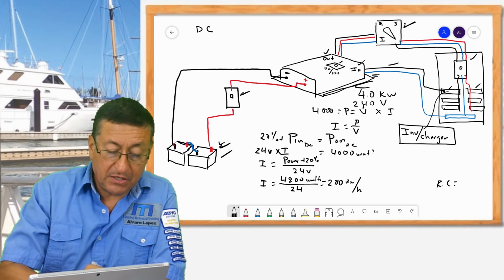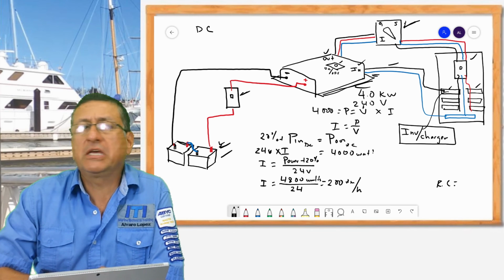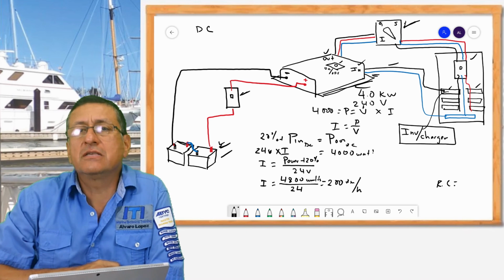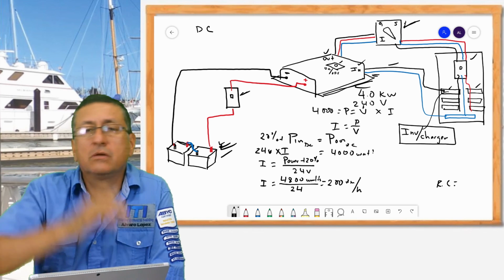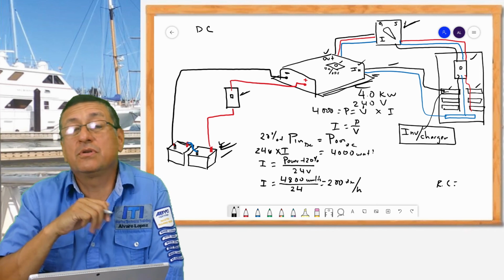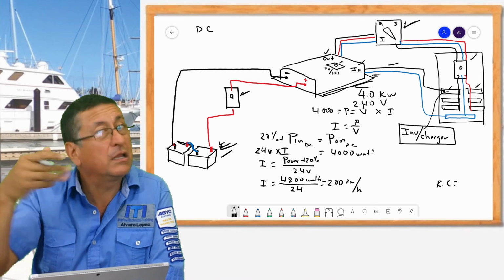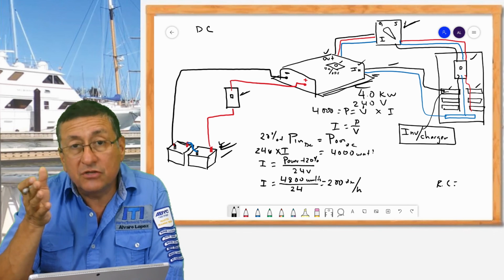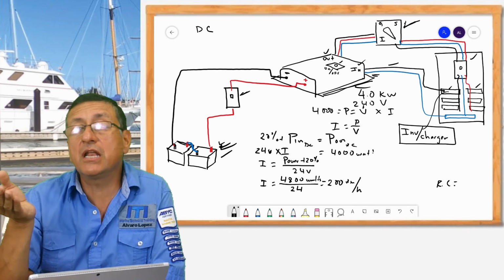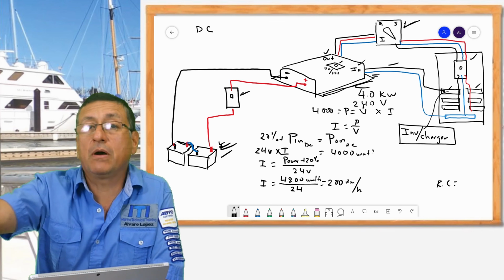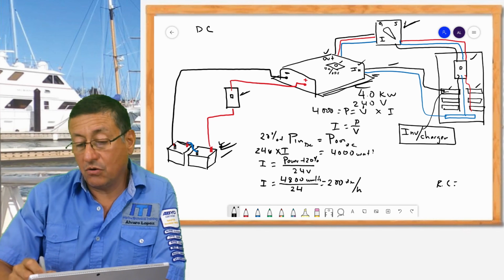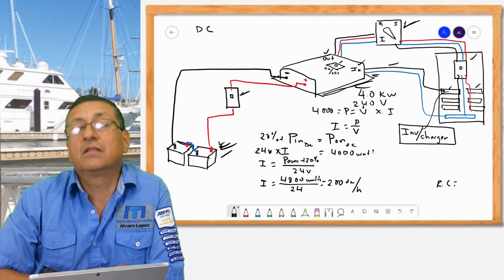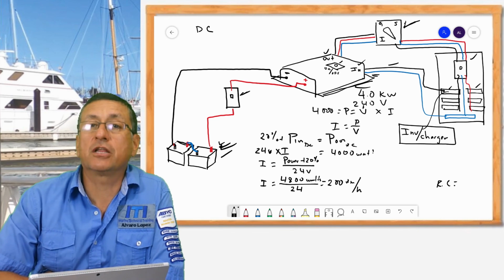You can keep those batteries fully charged when the sun is low, the level of intensity of the sun is low, the solar panel is not producing good power, the windmill is not producing power, and the inverter is not producing power. I am using the generator, or I am using the shore power line. I can activate this breaker, and the group of batteries will be fully charged.